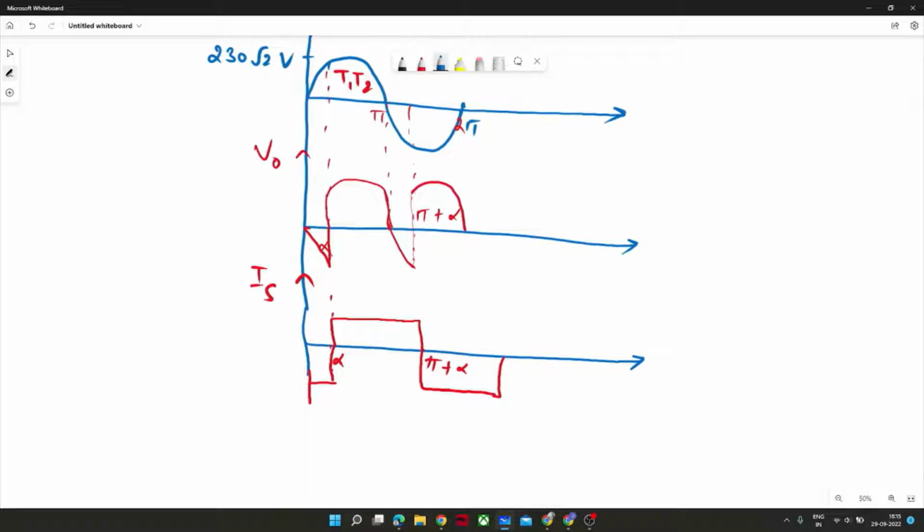So this is a square wave which consists of several harmonics of the fundamental component, and that fundamental component will also have some contribution, and I would say it would contribute majorly in any power electronics converter, because that is the point of using any DC to AC or AC to DC converter.